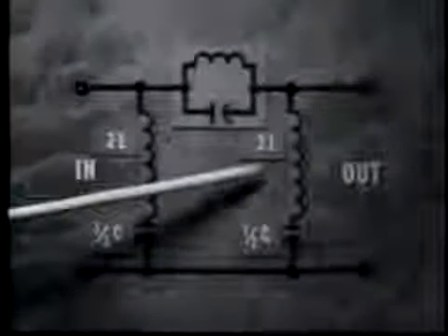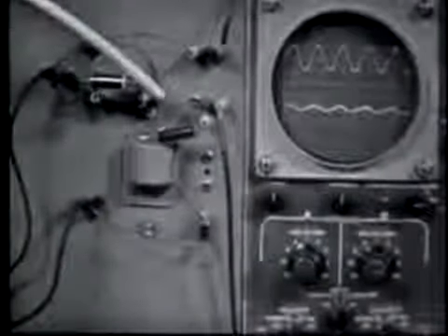The pi section band reject filter has 2 shunt legs. Each leg has a series tank with twice the total shunt inductance in each tank and half the total shunt capacitance in each tank. Again, this is done to maintain total shunt inductance and capacitance at the required values. Now we have our demo hooked up as a simple L section band reject filter, a parallel tank in the series position, our little shorting wire, and a series tank in the shunt position composed of this capacitor in series with this inductor, and of course the other side of the inductor going to ground, and our output is taken across our shunt component.